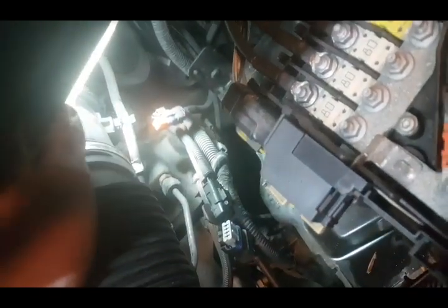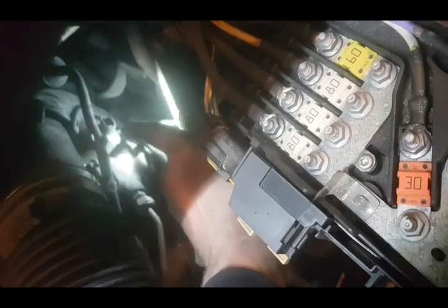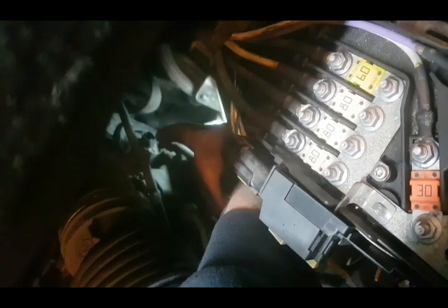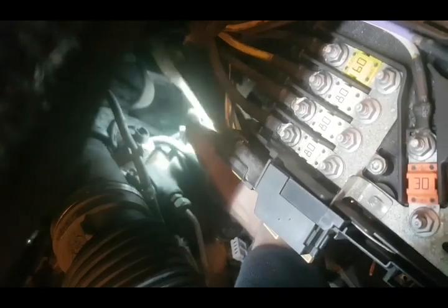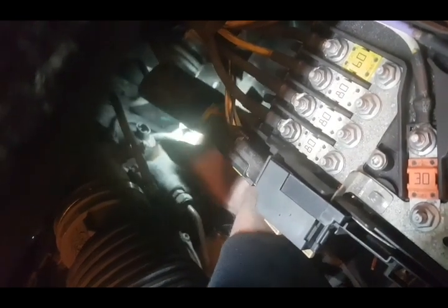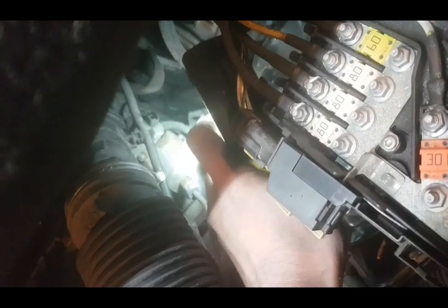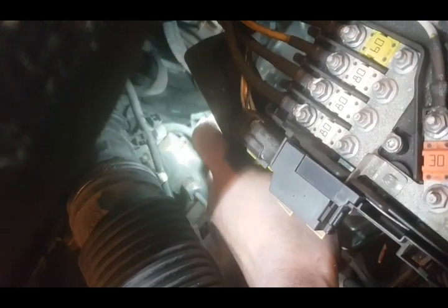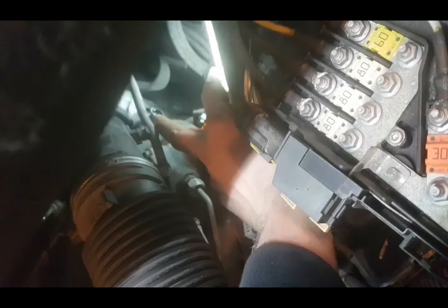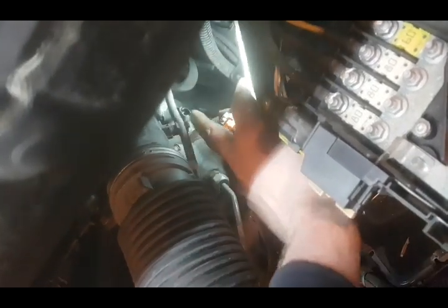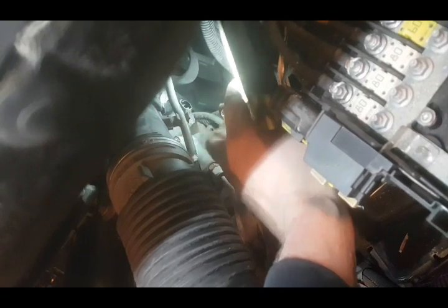The sensor, by the way, is, move that out of the way. That is the fuel pressure solenoid valve. Now, it's worth checking somewhere to start. I'd be suspicious it's sticking slightly open, which is why we're getting not enough pressure on cranking and an instant drop off of pressure when we stop cranking. But if we put the tiniest bit of sniff in, it fires up, no problem.